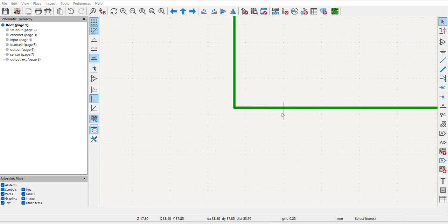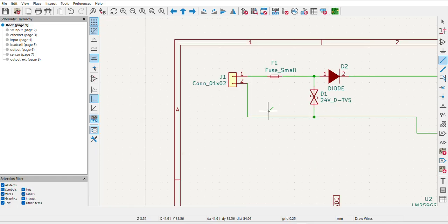But when I try to add some new wires, they are not adding properly. They are not mated with these wires at all. Here you can see it's not joining. So the problem here is my existing design is on some other grid, and now my grid settings are changed.